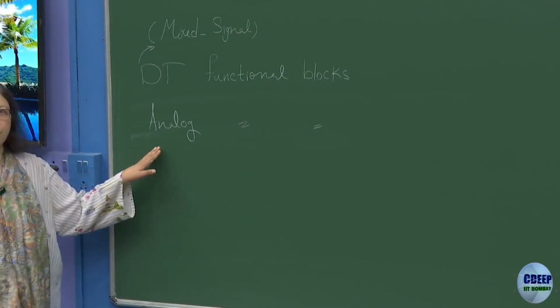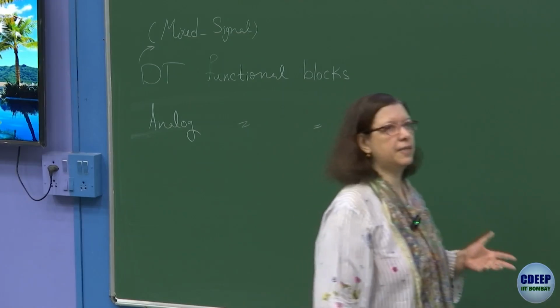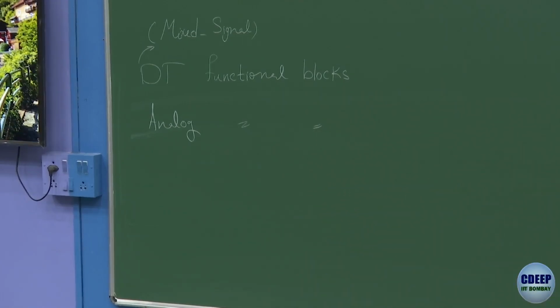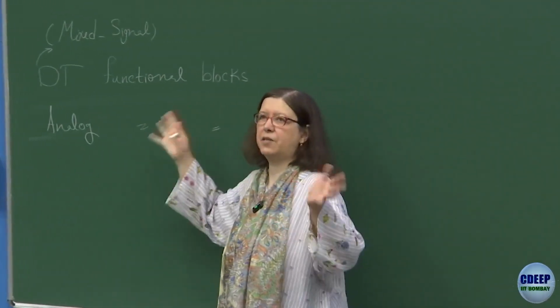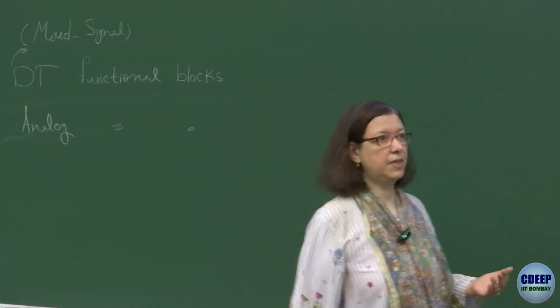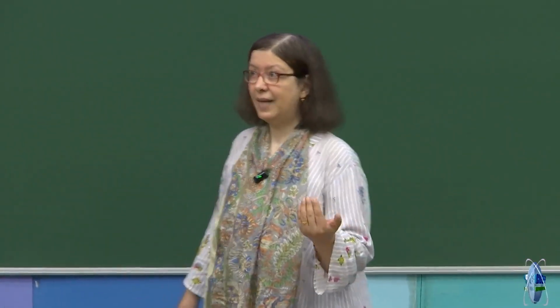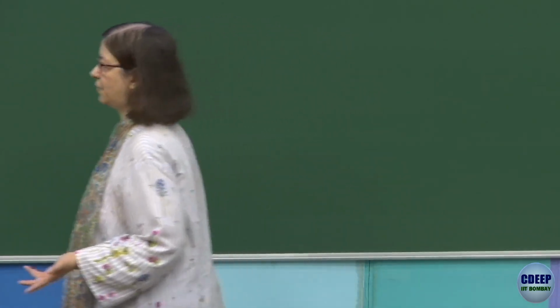And specifically, usually the terminology of analog is used when you deal with continuous time as well. So definitely in the literature, whenever somebody says analog, it's mainly continuous time. As soon as we move to discrete time, effectively everything becomes discrete time. And you notice when we discuss a circuit like a simple unity gain buffer, that discussion, analysis, operation, behavior is totally different from continuous time.